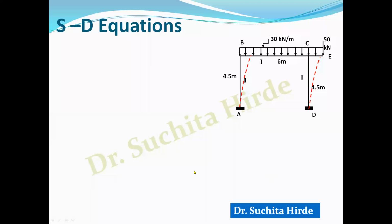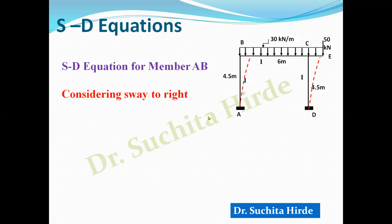Now the next step is to write the slope deflection equations. Whenever there is an overhanging part, while writing the slope deflection equations, neglect that part. This will appear while writing the equilibrium equations. Now you know that there are three members in this portal frame, AB, BC and CD. So the number of equations to be formed is equal to 2 times the number of members. So in this frame, we have to write 6 slope deflection equations.